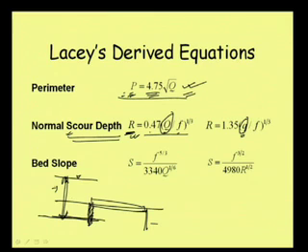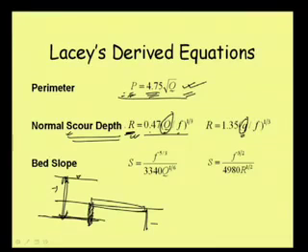That is why it is called scour depth, because this is the depth in regime condition. Of course, this is the normal scour depth, but depending on some other criteria, if there is a bend, if it is straight, then for design purposes we need to take some safeguard. So, we get the actual scour depth, and we can multiply it by some factor.